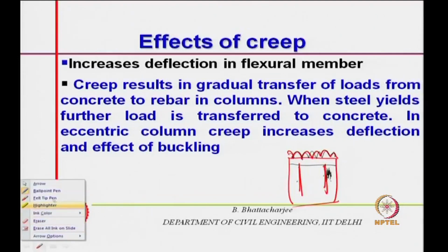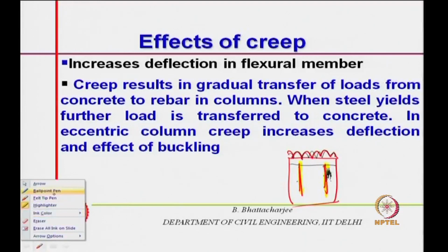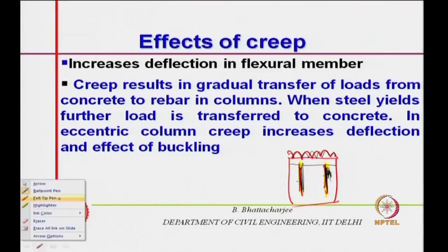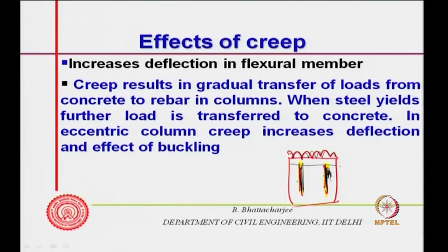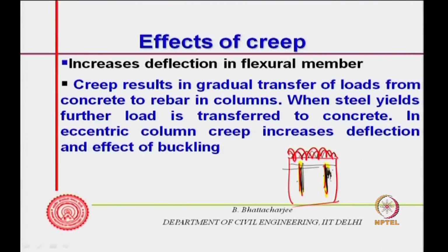So, this is your rebar, and this is the concrete. They will have the same deformation, because they are acting in parallel. So, if you have load like this, they will have the same deformation. So, deformation will be similar.